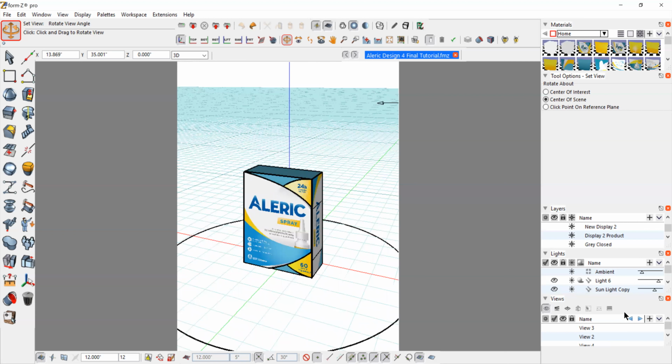My little dialogue here is at the very bottom, and I have several views set up here. So all you have to do is click on the plus sign, and it'll give you a new view number. And then when you like that, you click on this front area where this red dot would be. And then when you click on that, it'll kind of zoom in and out for a second, and it'll hold that view and save it for you.